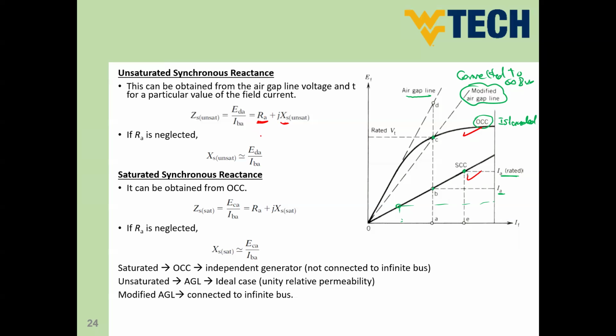And from the open circuit and short circuit, we can get the impedance. Once we got the impedance, we can calculate the reactance because RA would be measured using the ohm meter. So this is a way how can we identify the parameters. If we have a large synchronous machine, large means high power synchronous machine, the resistance is mostly neglected compared to the reactance. So we can say that if the armature resistance is neglected, XS equals Z.